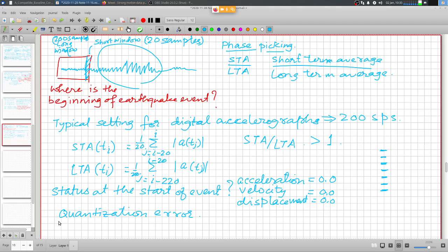That comes from the instrument, the components' fatigue in the instrument, or misalignment, or mechanical fault, mechanical misalignment of the components in the sensor, and so on. So there can be a DC offset, which is a constant shift.